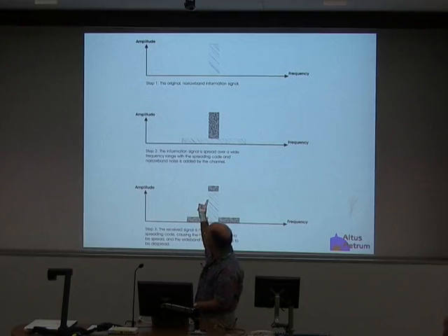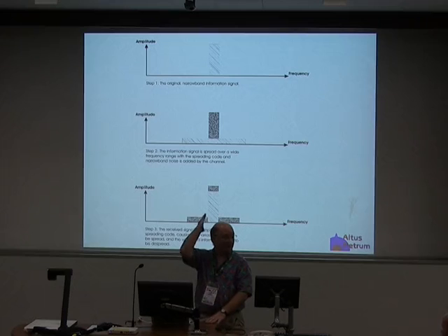You can get rid of these spikes, which means that direct sequence spread spectrum radios are very immune to jamming. Because if you just give me a huge carrier spike in the middle of my signal, I don't care. I can receive it anyhow.